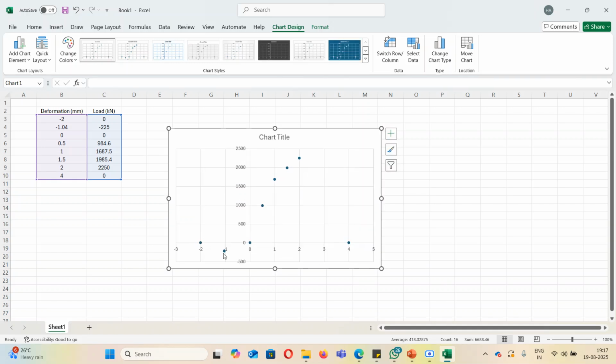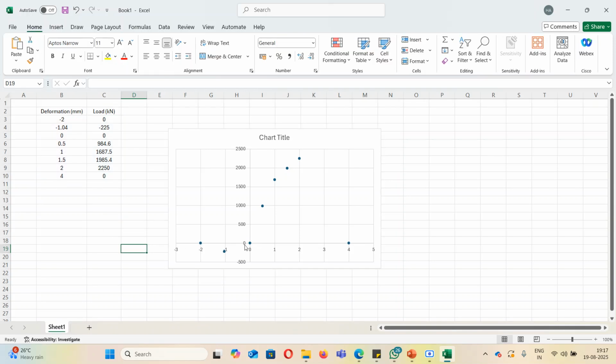So this is the stress versus strain profile that you will see. This is the parabolic plot in the compression side, which will drop as a linear profile after peak, and in the tension side there will be just a small stress that is taken, which will reduce to zero from here only. From here itself it will drop to zero and it will remain zero thereafter. So this is the load versus deformation profile, with deformation on the x-axis and load on the y-axis.